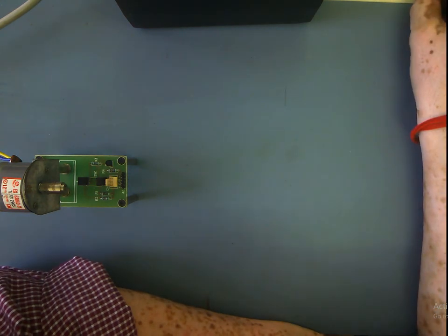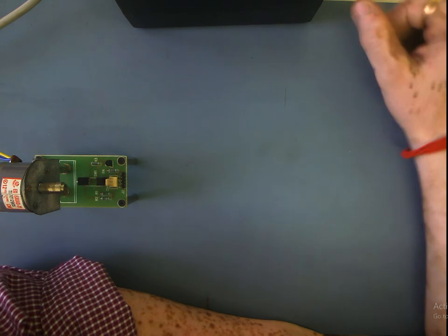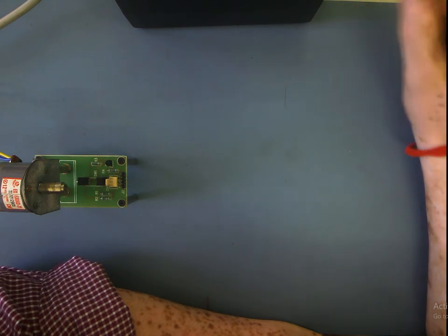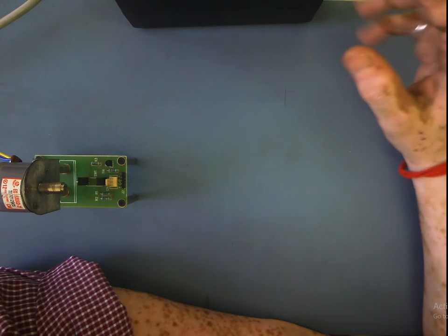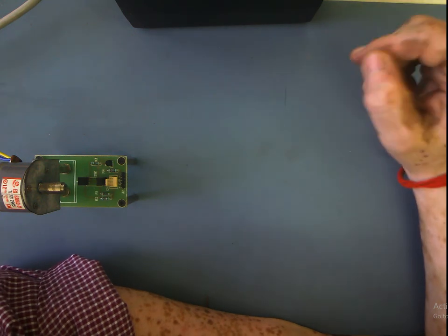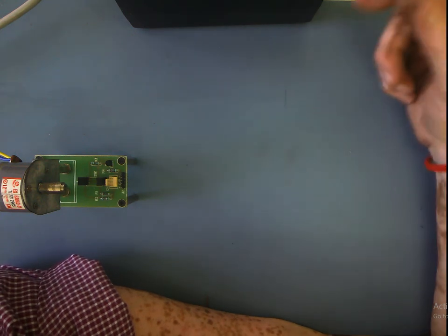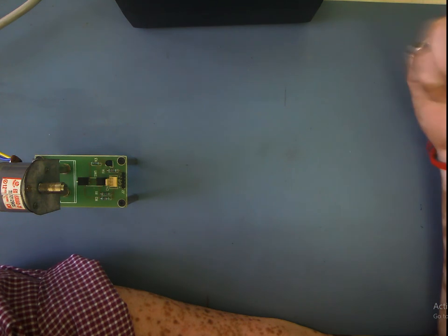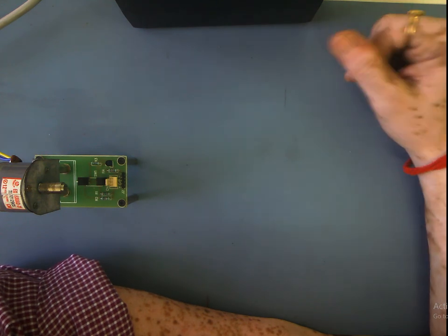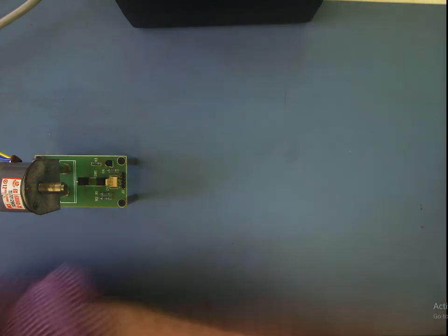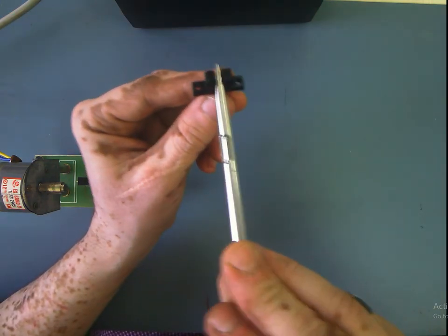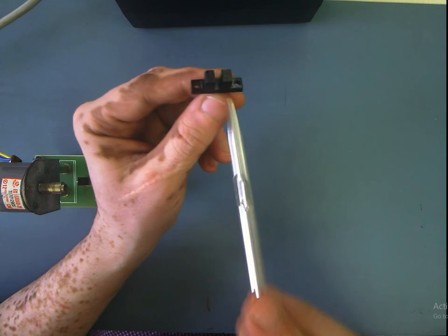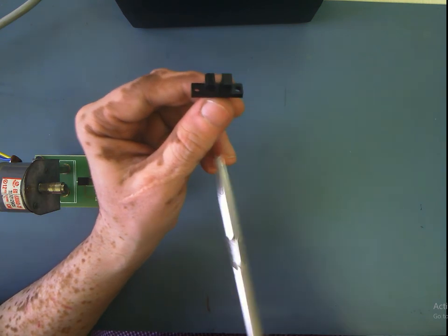As far as the collector of the phototransistor is concerned, we connect a resistance in series with the collector and then connect the resistance to the supply. Whenever there is an obstacle in between the source and the detector, here the IR diode is the source and the phototransistor is the detector.